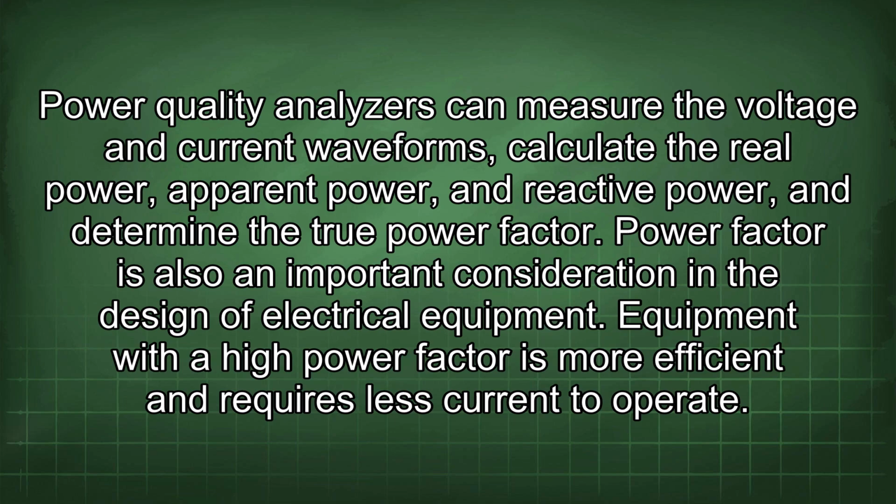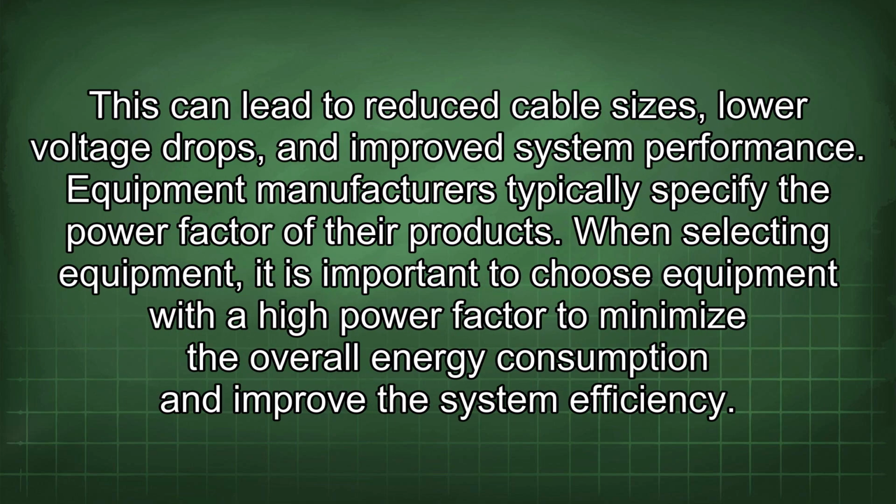Power factor is also an important consideration in the design of electrical equipment. Equipment with a high power factor is more efficient and requires less current to operate. This can lead to reduced cable sizes, lower voltage drops, and improved system performance. Equipment manufacturers typically specify the power factor of their product. When selecting equipment, it is important to choose equipment with a high power factor to minimize the overall energy consumption and improve the system efficiency.